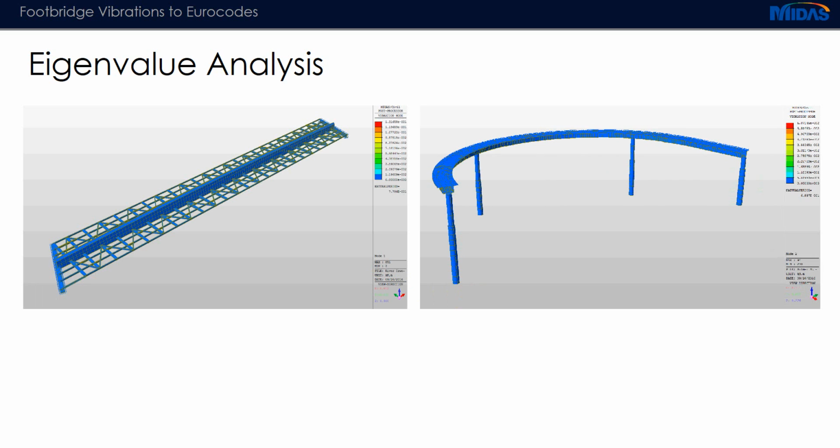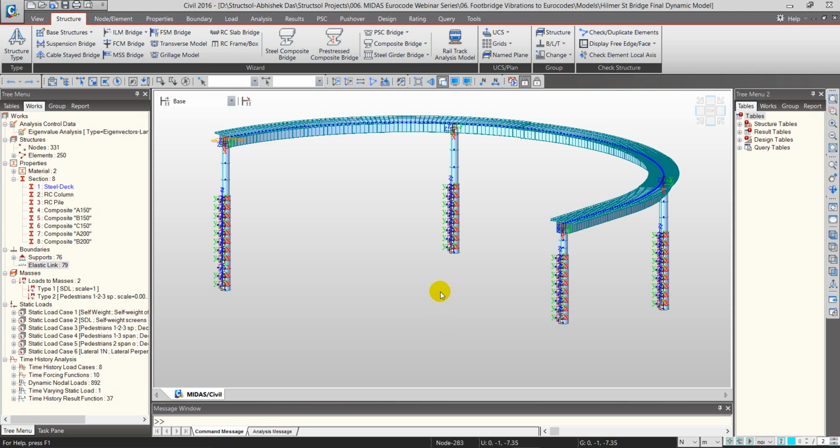So let's see how in the software we can carry out such an analysis. For eigenvalue analysis, it is important that the stiffness, boundary conditions and the mass of the structure have been defined correctly. In the previous few slides we saw how the model is set up initially, so that we have the correct stiffness and mass in it.